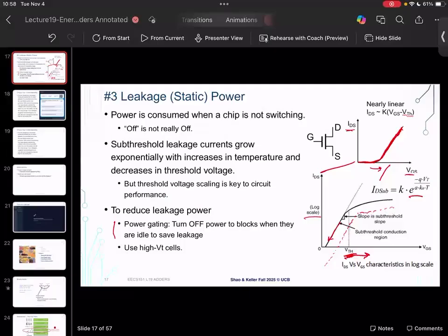Hello. Question? Yes. I've seen different definitions where you take half of the resistance, so it's basically the sum of the resistors, and then you multiply that by the capacitance. Summing the resistances and summing the capacitances. Yeah, you can define it either way. You get approximations where one is more accurate in some circumstances and one is more accurate in other circumstances. So in this example, I got like 7 RC. Which one would be more accurate?